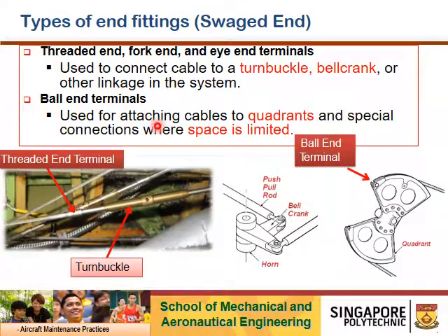Types of end fitting, swage end. Most of the time the cable can have a ball end terminal, or you can swage on a threaded end terminal with attachment of turnbuckles. We will show you more about the end fittings during the practical sessions. Swaging is actually a compressive force that deforms the fitting to ensure that it clamps hard onto the cable.